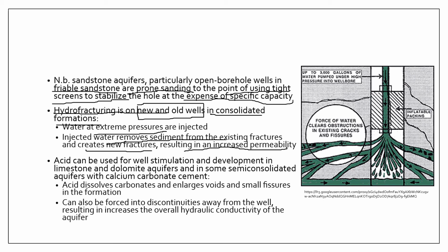All right, so this is how hydrofracturing works. You basically just inject water at high pressures, and this typically involves a bladder or an inflatable packer to ensure that the pressure is just directed towards the fractures.